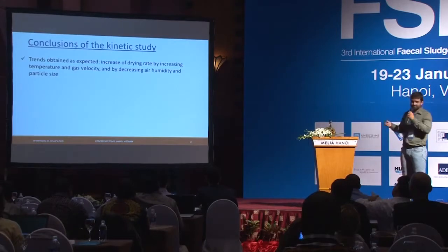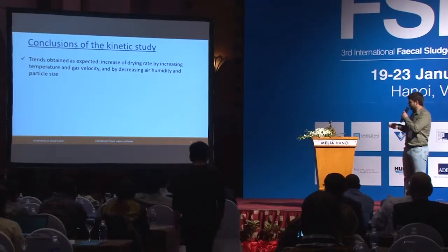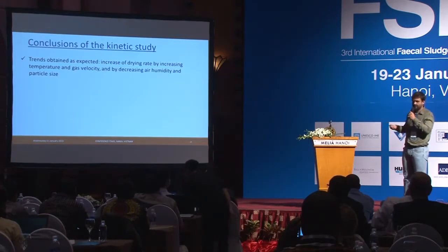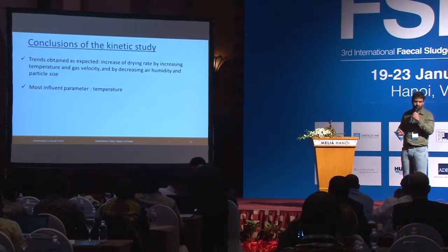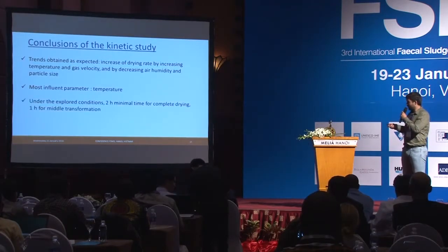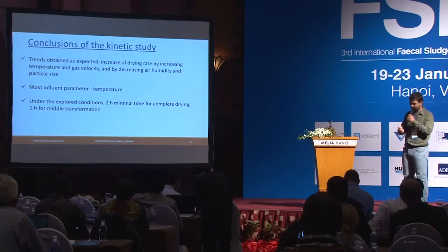The conclusions of the kinetic studies: we didn't find anything extraordinary. We found what we had expected. That means that we increase the drying rate by increasing temperature and gas velocity, and we decrease the drying rate by increasing the humidity and particle size. The most influential parameter was temperature compared with the others. Under the explored conditions, in the most pessimistic cases, we have 2 hours of drying, and in the most favorable condition, it was 1 hour of drying, and we have to know this order of magnitude of time for the processes.